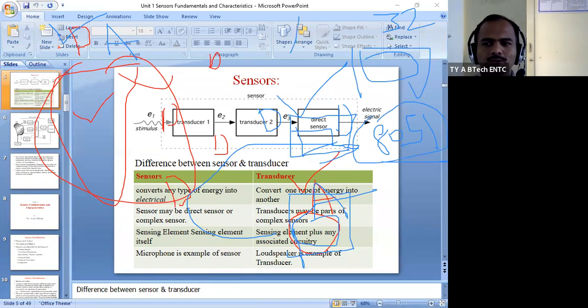Or sometimes if you go with 4-bit mode, then instead of using an 8-bit data line, we may go for a 4-bit data line. So 4 lines are saved from your controller side. So minimum, how many lines are there? 7 lines to interface an LCD with 8051. So out of 32, if 7 are gone for this, how many are still remaining? 25. Again, some 2-3 motors and other 3-5 signals are gone.